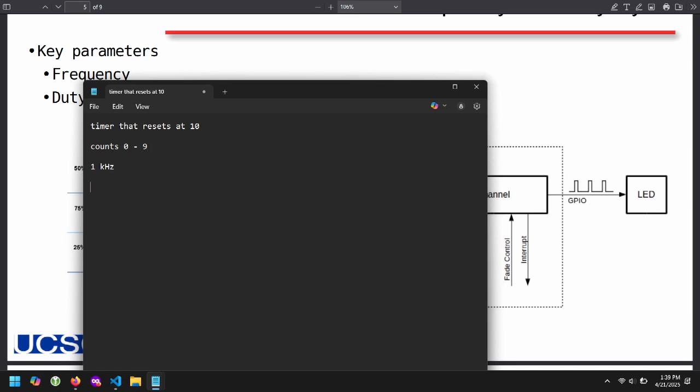And then let's say that PWM is high when counter is greater than or equal to 8. Okay, so this would be the sort of configuration that you would put into your timer. I'll put this in brackets. So this would be a configuration that says at what point we want PWM to be outputted. Then you would also have a configuration right here that would say when the timer actually goes and resets.